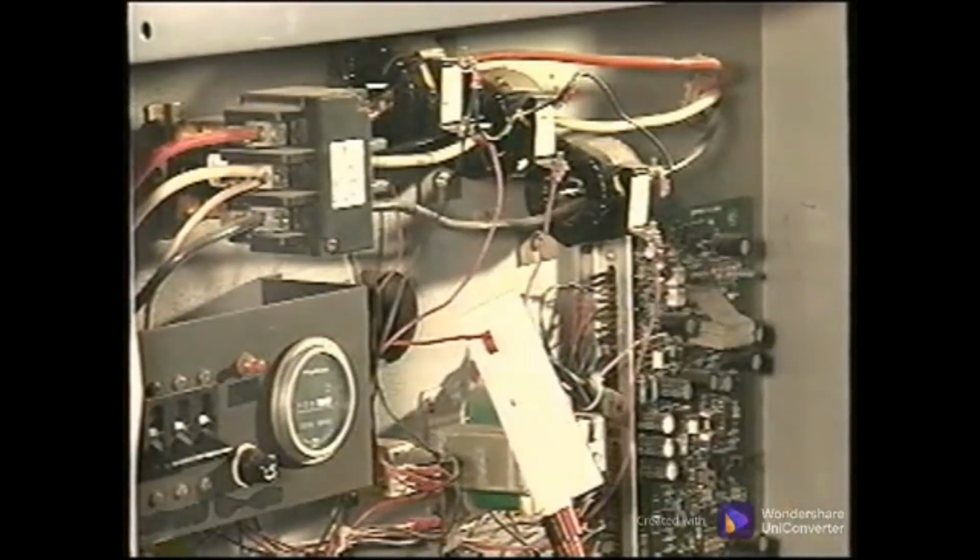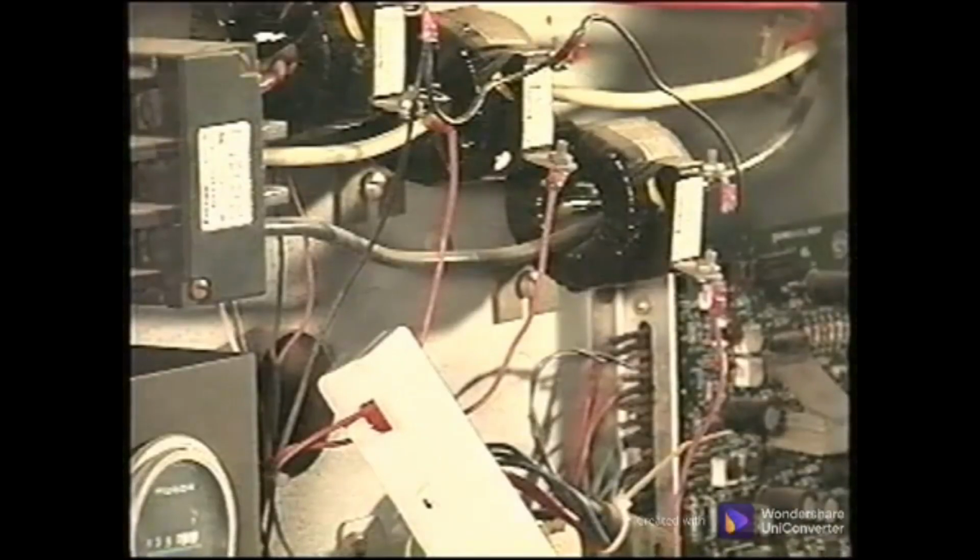All 3 phases of the power supply should be equal or balanced. If they are not equal, for example 60 amps and 50 amps, it indicates either a problem in the line power or a problem in a phase winding of the motor.